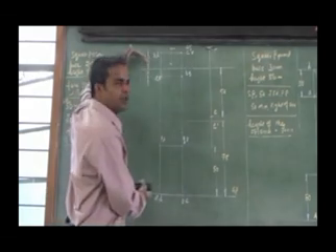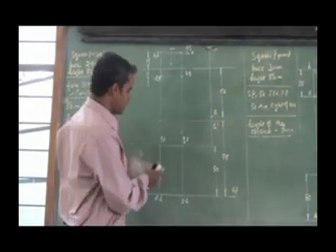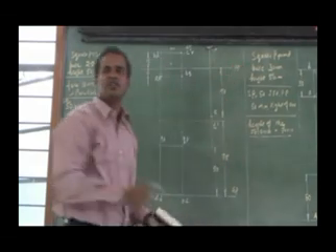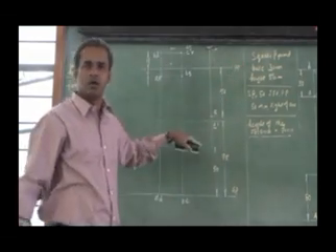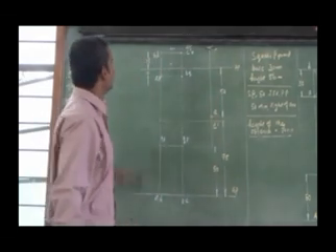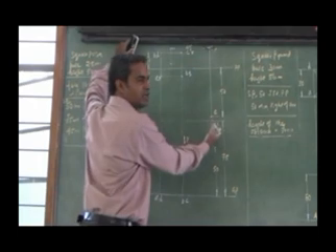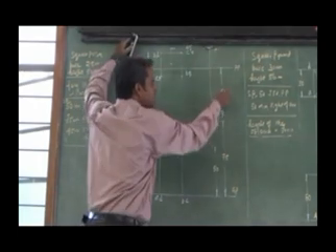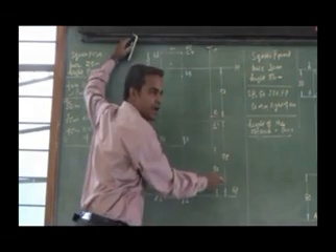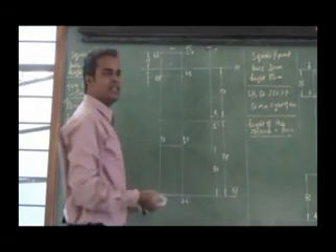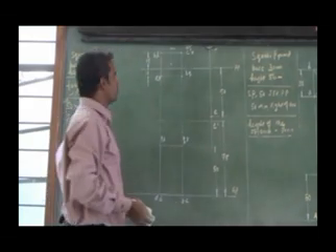But maintain the gap in between that is more than the above and in-front distance of the station point, because E and E dash should not interfere. Then the station point location is given: to the right 45 mm, the in-front distance is 50 mm and the above distance is 75 mm. So the layout is drawn, then you get the perspective view.